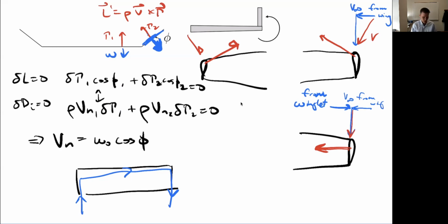This is the one that's closest, right? Because if I take that wing and rotate it, all of them are going to have an effect. But the one that's closest, kind of the biggest effect, is going to be this one. So let's just consider that. So if I rotate it, it's going like this. It's still going to be going now in this side view into the page. So the winglet is generating a vortex that's going into the page. So it's kind of like this. This is the direction of the induced circulation from that one bound vortex.